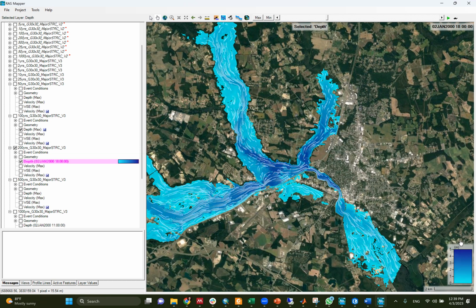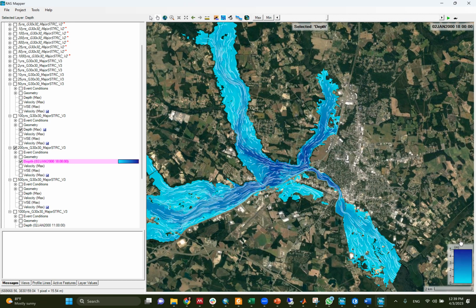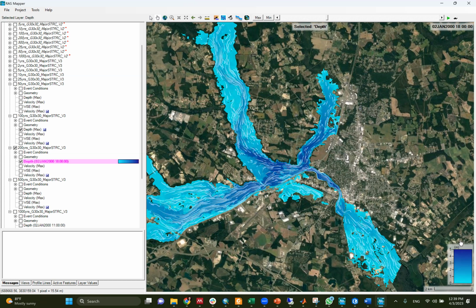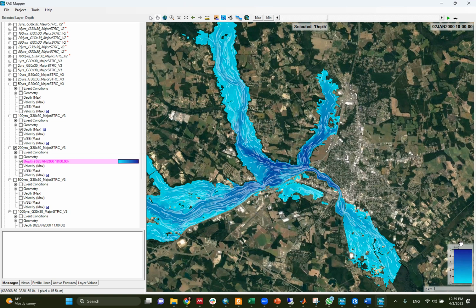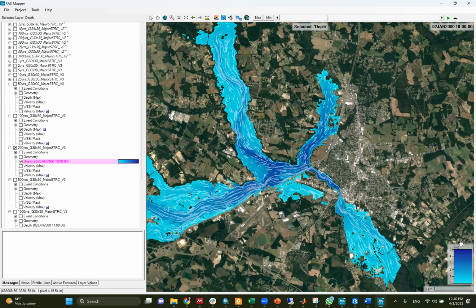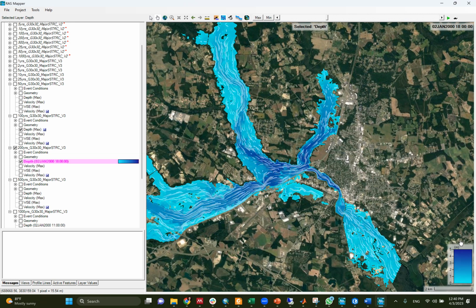If they do not look good, I will send every one of you the accurate hazard maps that I have, because they are very detailed. They include lots of parameters like land use, land cover, and different Manning coefficients, because every part of this area has a different Manning coefficient. Here are roads, and the pavement of roads has a different Manning coefficient from the forest, and a different one from urban areas. All of this affects how the water flows. So my maps will be much better, and I will send each one of you a different hazard map.